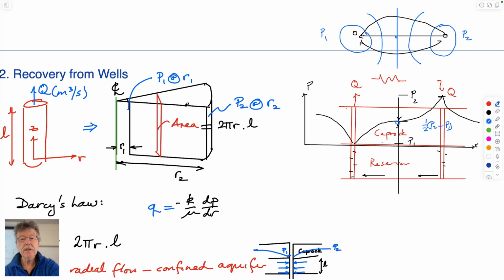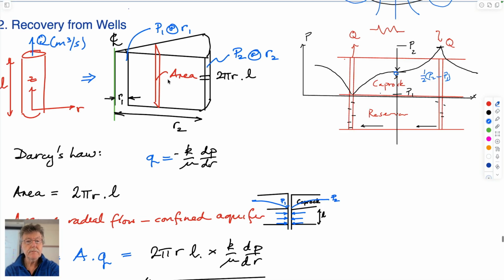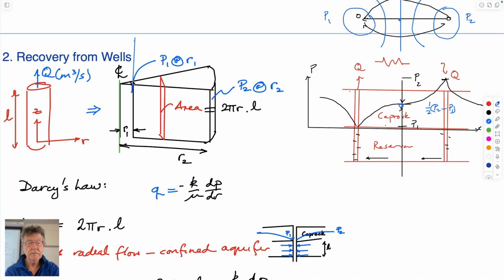And so we can isolate a single slice of the cake which represents this behavior. The solution to this is pretty simple. We can use Darcy's law, permeability, viscosity, pressure gradient, which is defined locally. The pressure gradient above here, if we draw it on top of this, would look something like this. So this is the pressure change. This is the radius over which it occurs. This is always true everywhere on this curve, but of course the gradient changes as you go along this curve.